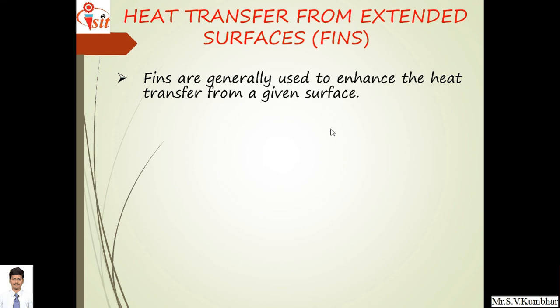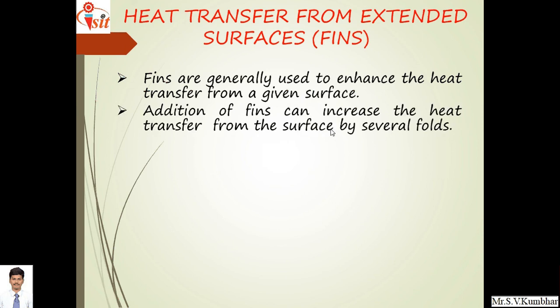So fins are generally used to enhance the heat transfer for a given surface. As I mentioned earlier, if you provide more surface area, then generally the rate of heat transfer increases. Therefore, fins are generally used to enhance heat transfer for a given surface. So addition of fins can increase the heat transfer from the surface by several folds.